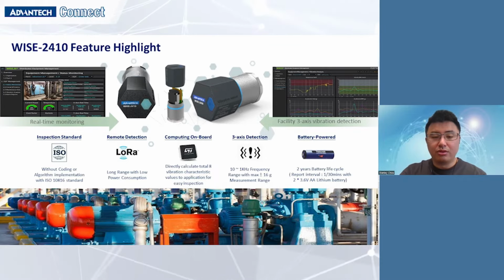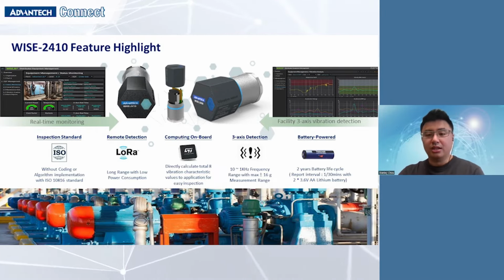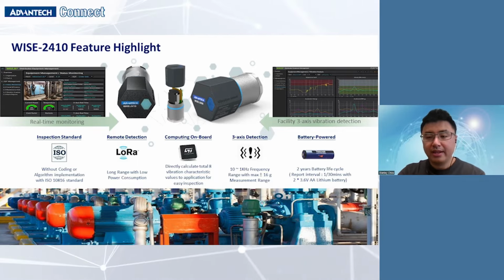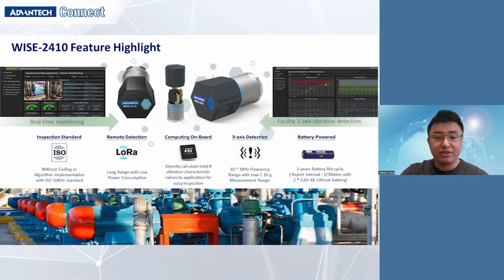Second, with long-range, wide wireless coverage and low power consumption LoRa wireless technology, the WISE-2410 can be powered by only 2 AA lithium batteries. The battery life can be up to 2 years with a data update cycle of once per 30 minutes. And third, the 2410 is a 3-axis detection solution with a 10 Hz to 1 kHz frequency measurement range. In conclusion, the WISE-2410 is a smart vibration sensor that can identify equipment conditions by monitoring in the cloud or on premise, and then plan and perform maintenance efficiently.